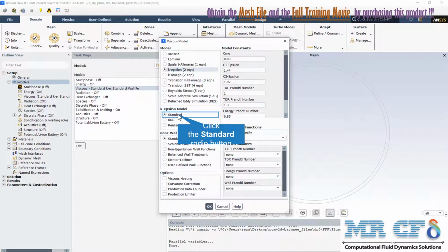In the viscous model, the standard K epsilon model has been used. That is a two-equation turbulence model that allows the determination of both a turbulent length and time scale by solving two separate transport equations. The standard K epsilon model in ANSYS FLUENT falls within this class of models and has become the workhorse of practical engineering flow calculations in the time since it was proposed.